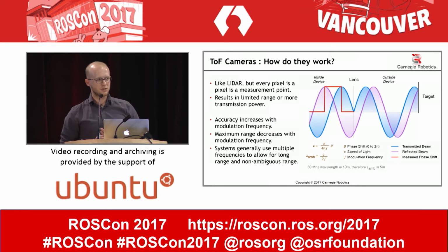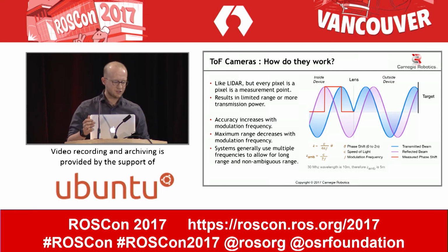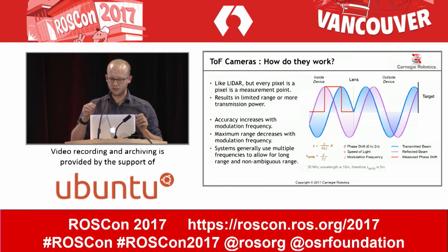So time-of-flight cameras are similar to 3D lasers from an emission and detection perspective. But instead of having a laser emitter, they have a modulated IR emission, and then you're actually doing that phase-based extraction on every single pixel in a photo array instead of on a single avalanche photodiode.